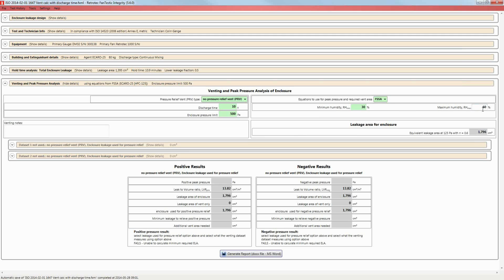So it would be unusual for a room to only exist in high humidity. Usually there'd be a range from min to max, and they would be your design minimum, which would be the humidity that the room is likely to not fall below, I think, 95% of the time, and the upper one is the highest humidity that you would expect 95% of the time as well. That may actually be kind of a hard value to figure out, but